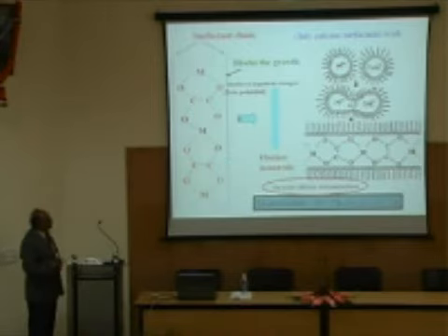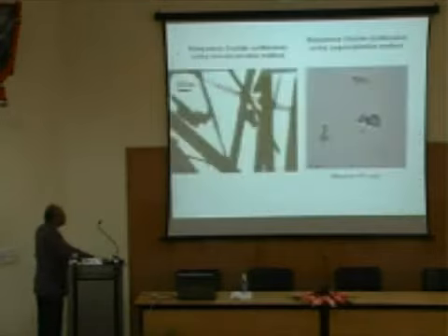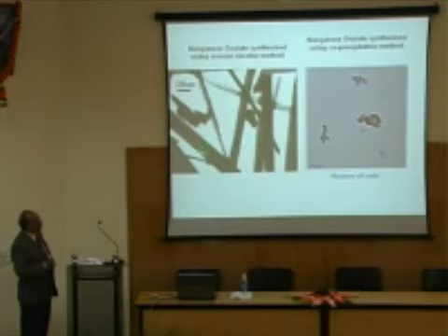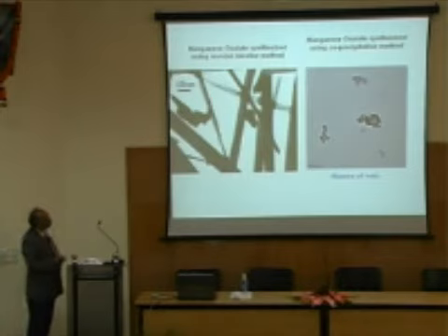So there is a tendency to form or grow in only one direction. Okay. So you see these rods which have diameter of around 60-70 nanometers, but they are very long. These are TEM pictures. Note that if you don't use microemulsions, if you use a standard chemical route, then you will not get these rods, you will get only particles. Okay.